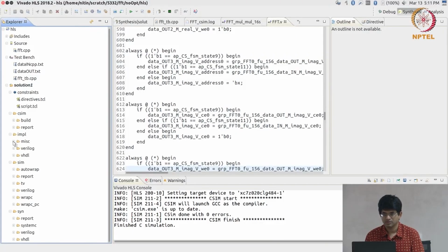What we would like is, can we have some kind of simple confirmation that the Verilog that got generated actually does what we wanted it to do? Now this is something called equivalence checking. In the general case, equivalence checking says that I have two versions of a design, and I need to check whether they are doing exactly the same thing.